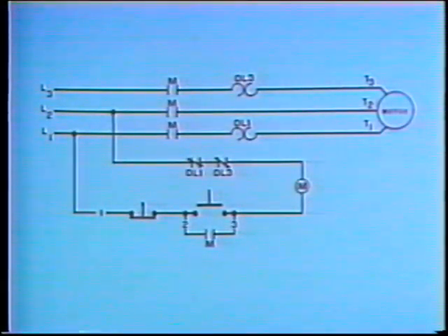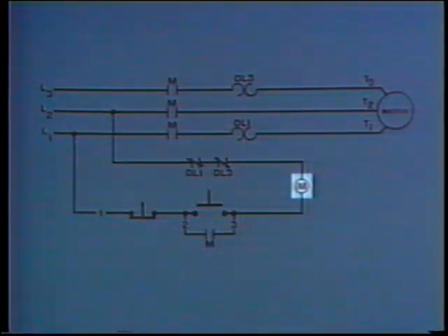Now that we've located the parts of the motor circuit by using a wiring diagram, let's look at the control circuit. We'll begin once again by referring to the controller's schematic diagram. On the schematic, you can see that in the control circuit is the magnetic contactor's operating coil. In series with the operating coil are the overload contacts and a momentary contact master switch, and a sealing or